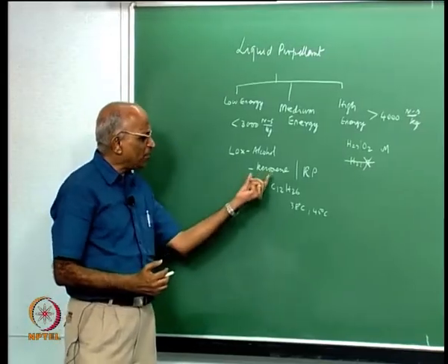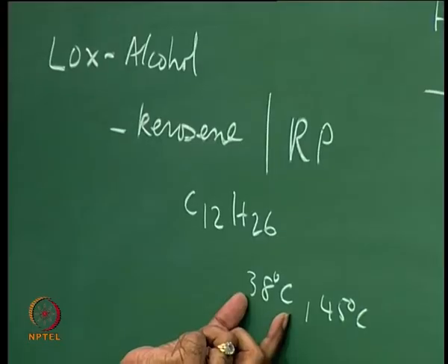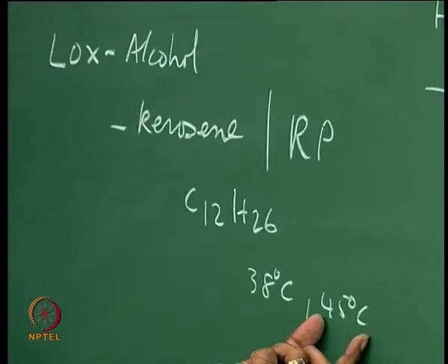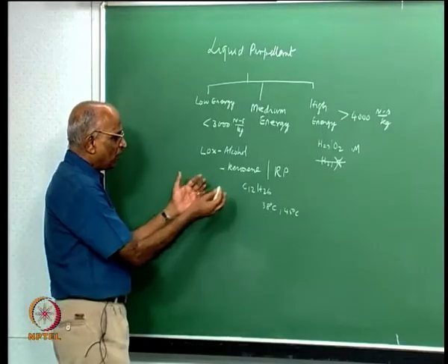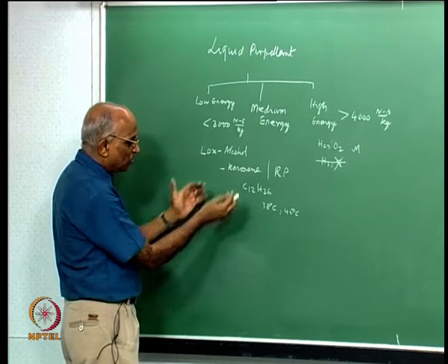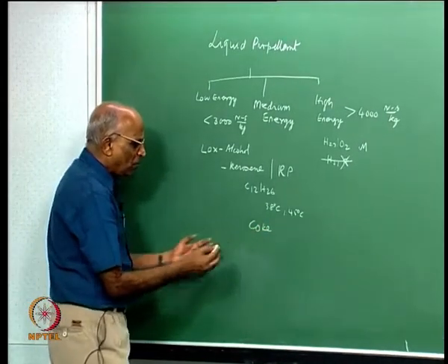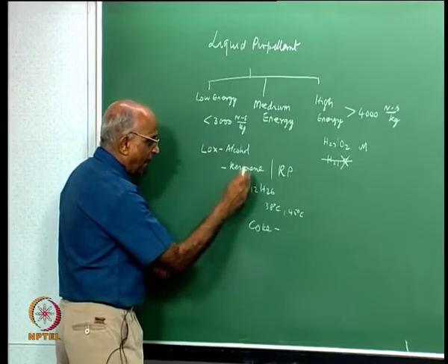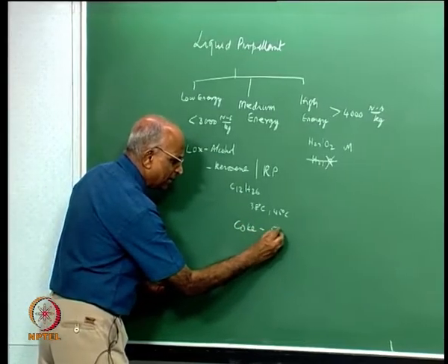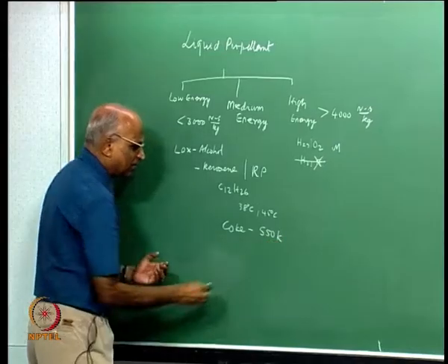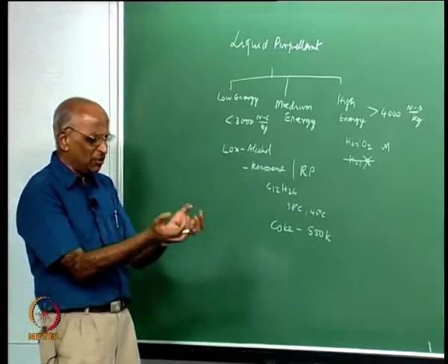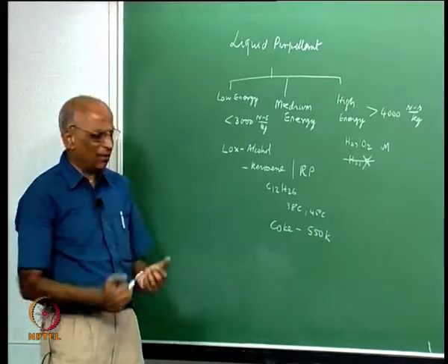Therefore the flash point of kerosene is around 38, and we increase it slightly to 45 or higher. Also, when you heat kerosene in the absence of oxygen it should not form a solid like coke, and by adding additives we make sure the coking temperature is greater than around 550 Kelvin, such that when you inject, it should not block anything if it is heated.